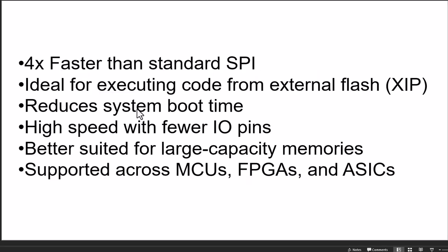So why do we need this QSPI? Actually it is four times faster, and one additional thing is that we can execute the code from this flash, that is known as XIP. As we know, it is faster than SPI, so we can use this for system boot, and the system boot will take less time.